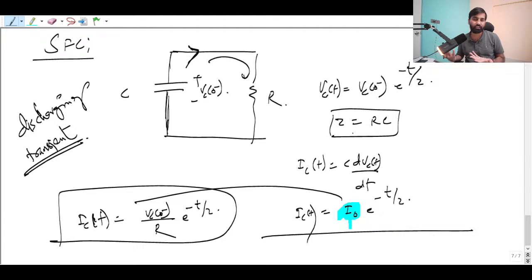Power integration, that is charge. How much is the total change of charge, like how much charge you need from the capacitor. So you take the charge from the capacitor. There was initial charge 100 micro, and you have taken out 50 micro, right? So 50 times 5 is the correct answer.